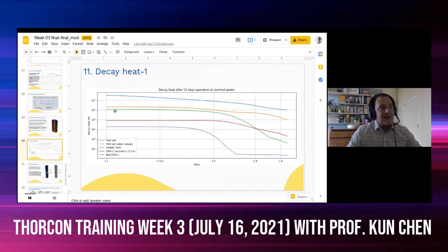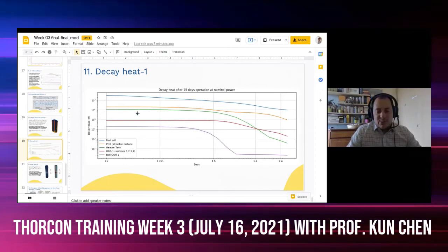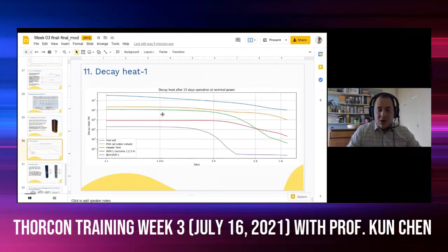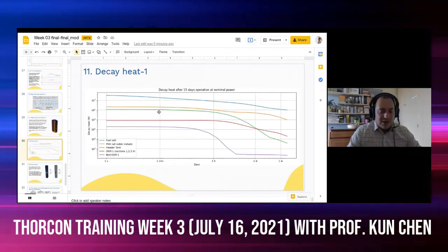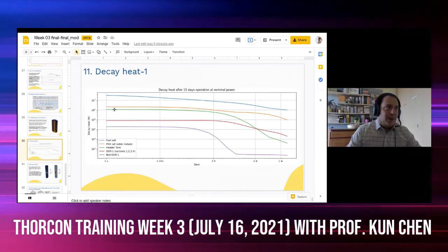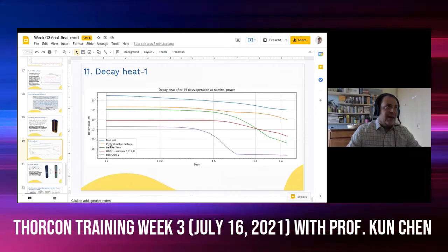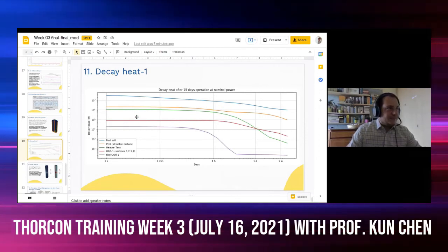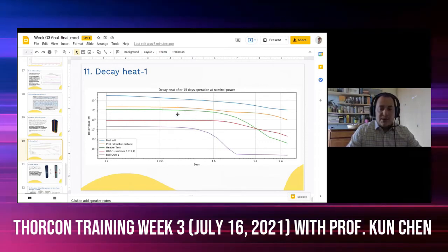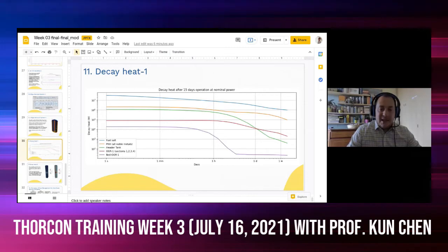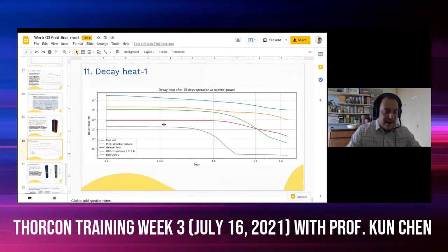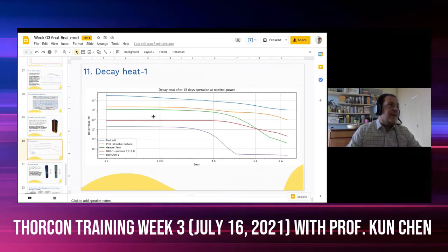Here we are assuming that all insoluble fission products are plating out. This is an extremely conservative assumption from the Oak Ridge era analysis. Not all the noble metals were plating out in the PHX. Nonetheless, this poses the necessary requirement to consistently size the decay heat handling for this component.